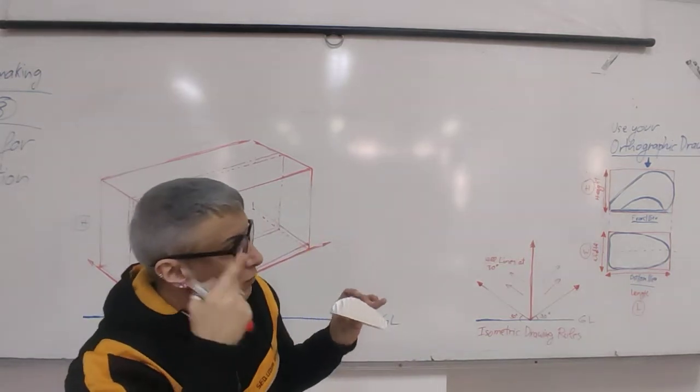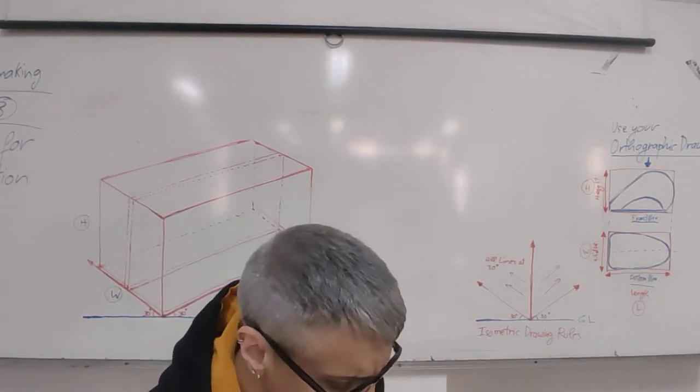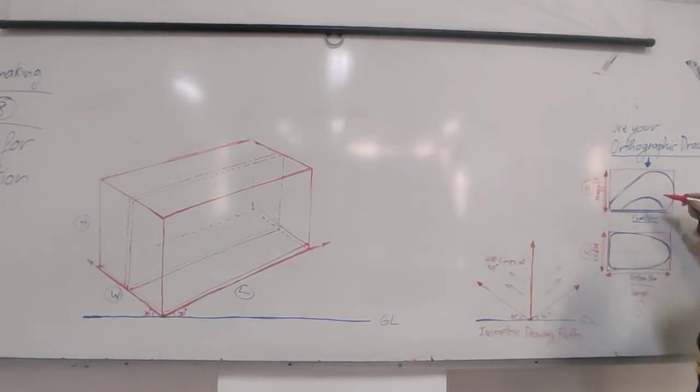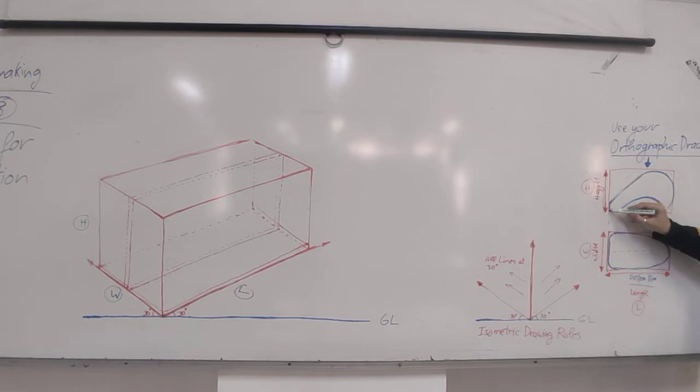First, we have this shape. Now in the orthographic drawing for model construction, we did what? We had divisions, the section divisions, okay? So we started at the front, 2 millimeter, then 5 millimeter space, then we draw another 2 millimeter, then 5 millimeter space, another 2 millimeter, 5 millimeter space and 2 millimeter, and so on until the end.